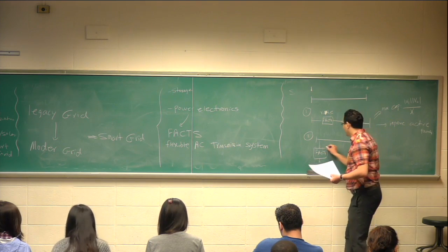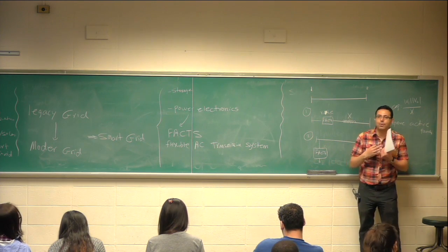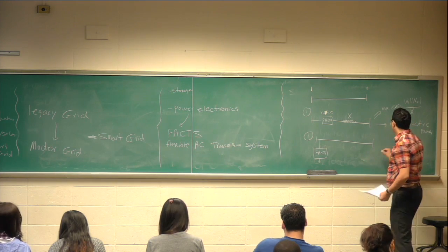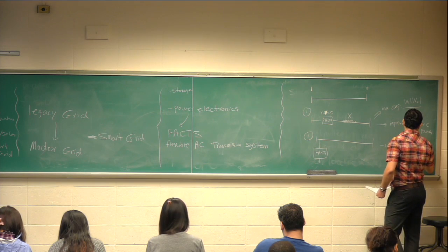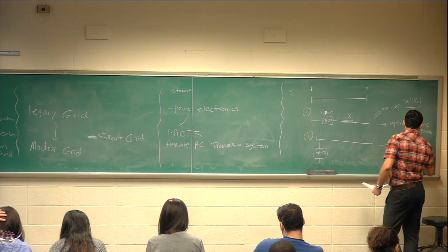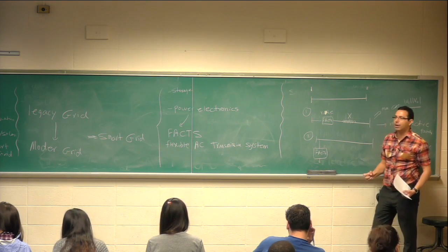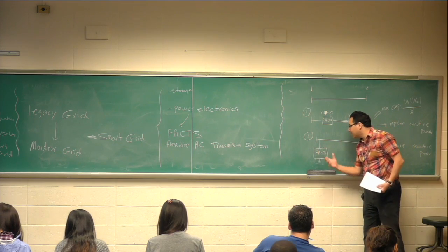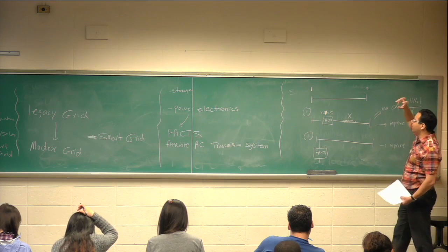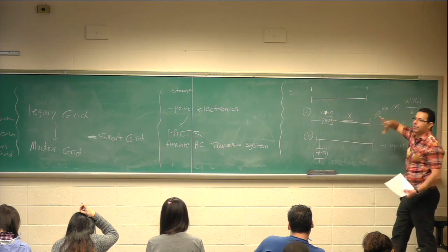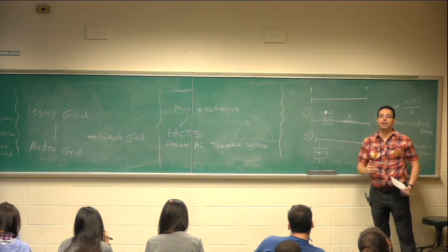Put a capacitor. If I put a capacitor here, capacitor is the source of reactive energy. So this improves reactive power. So we can improve reactive power if I have a capacitor here. So if I put some capacitance inside this, I'm storing reactive power. That improves reactive power. So as a series element, this device deals with active power. The same device as a shunt element deals with reactive.